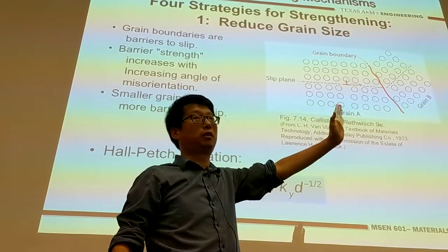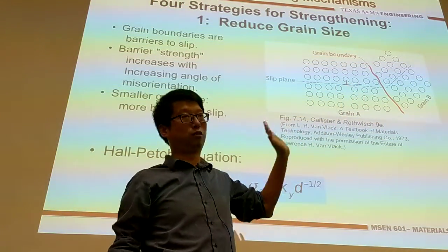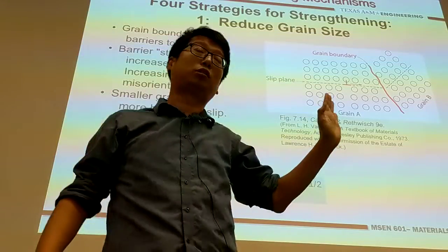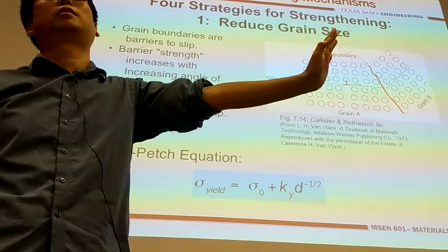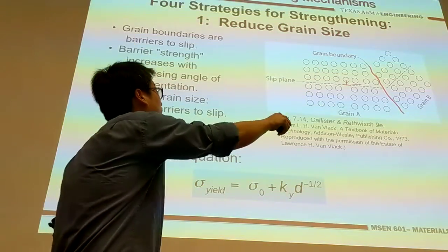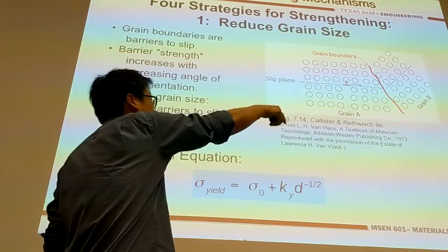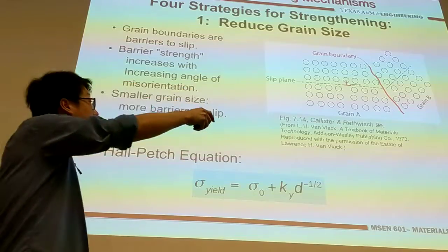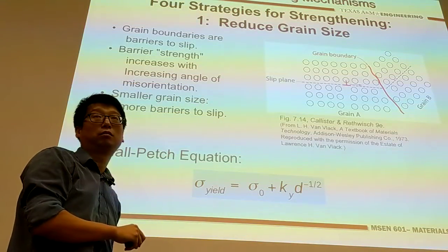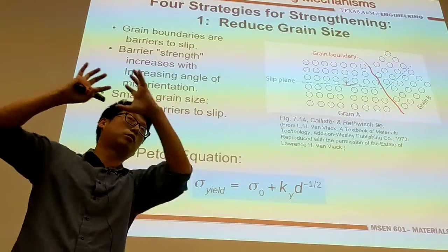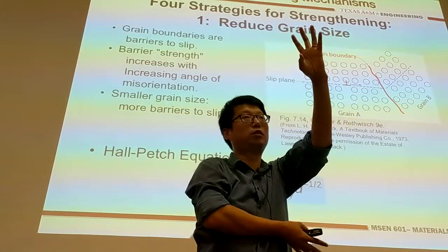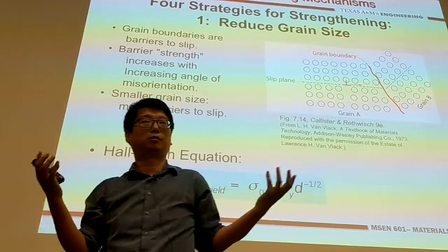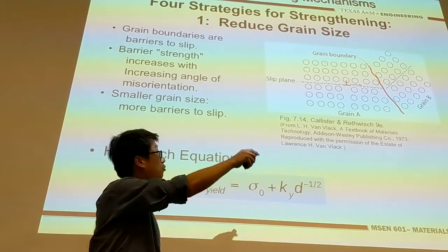In a single crystal, once you reach the critical resolved shear stress, that will propagate easily, right? However, for a non-single crystal, for example, a polycrystal, then you naturally have grain boundaries. If instead of a single crystal, you put one single crystal and another single crystal together, and form a grain boundary, then we call it a polycrystal. With a polycrystal, we have grain boundaries.